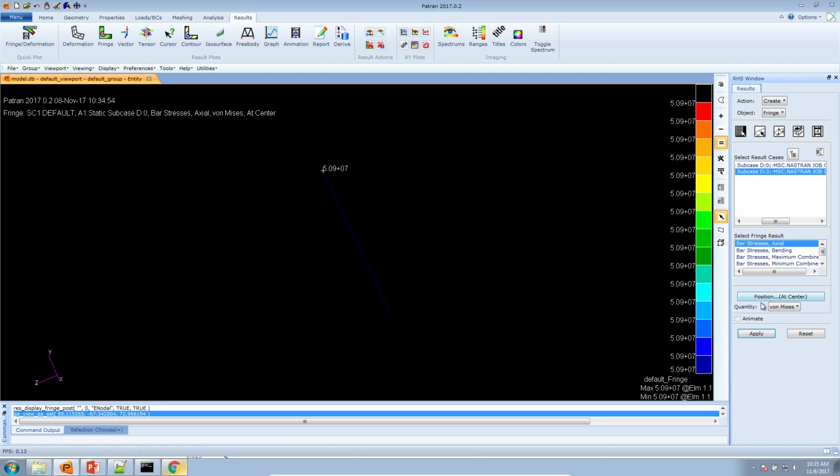So now let's go ahead and plot these stress results. You can see that if we look at the before results, we have a stress of about 50 E6. Our new stresses are about 110 E6. So the optimizer has minimized the radius until one of the stress constraints was violated, and that's what happened here.